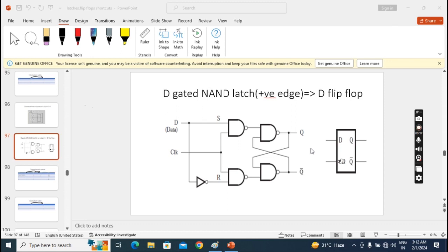In shift registers we want to shift the same data, but after some delay, from right to left or left to right. So the D flip-flop is exclusively implemented for shift registers and for some counters also. Some counters means the ring counter and Johnson counter. Those two counters are also called shift register counters. There also we use the D flip-flop.